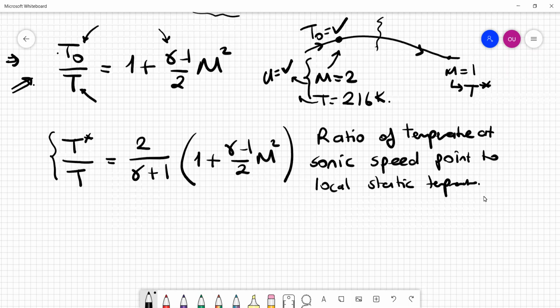Then you reach a certain temperature level, which will be quite high, because initially the fluid particle had internal energy plus kinetic energy, but if you force the kinetic energy to be zero, where will that energy go? It will turn into internal energy. The fluid particle will become very hot. The question is, does this happen in a flow field?